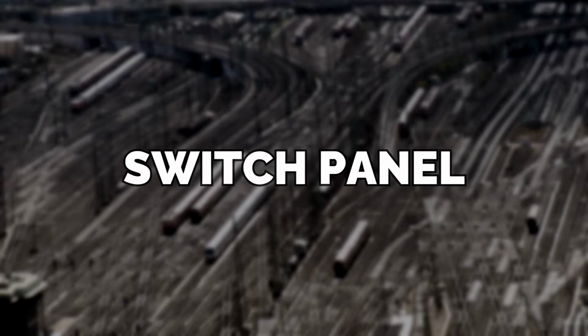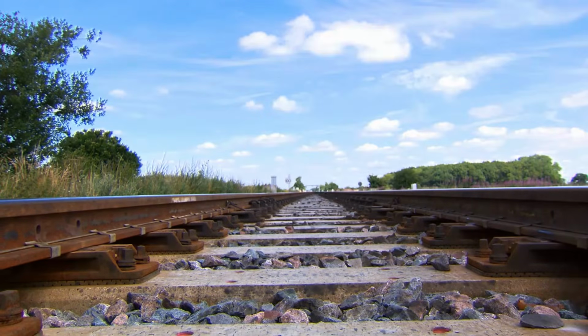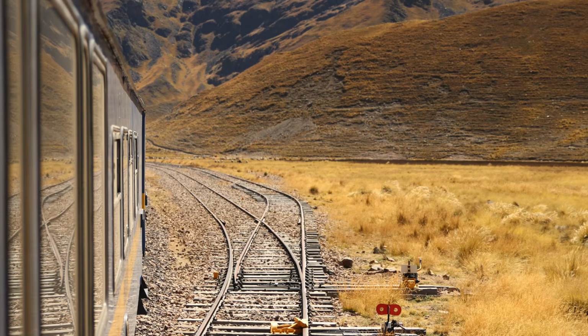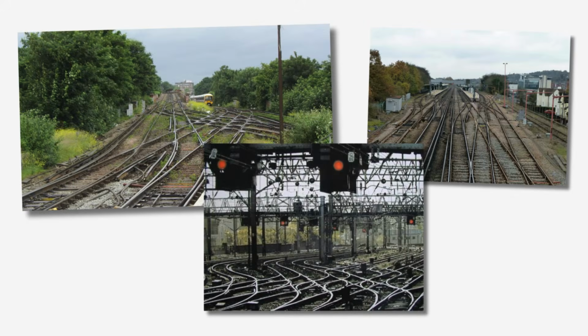First up, we have the switch panel. Within the switch panel is one of the very few places on the railway where the rails are actually designed to move. To determine which route a train takes, the switches move, allowing one of two routes to be taken. That is a key point to remember when it comes to junctions. With multiple routes, each switch allows a choice of two routes.